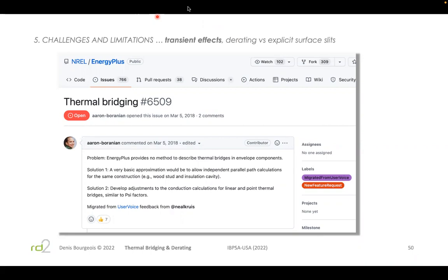Assuming the original code U and R requirements did not account for linear and point heat loss, are the incoming code UT values being increased now that the thermal bridging needs to be included? And the answer is no. So a couple of white papers and public review comments were submitted to the standing committee that writes the Canadian codes. And I think it was essentially set aside as being, well, it's up to the designers to design facades differently, or better mitigate the thermal bridging.